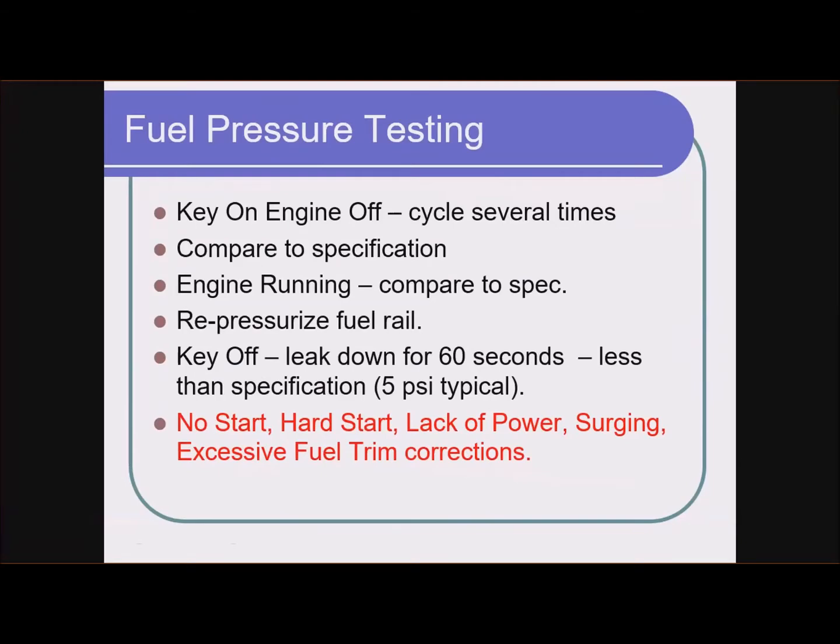The high pressure line coming out of the pump was cracked between the pump and the outlet of the tank. So a lot of the fuel that was coming out of the pump was coming directly back into the tank and never actually leaving the tank. So the pressure up at the rail was ridiculously low.